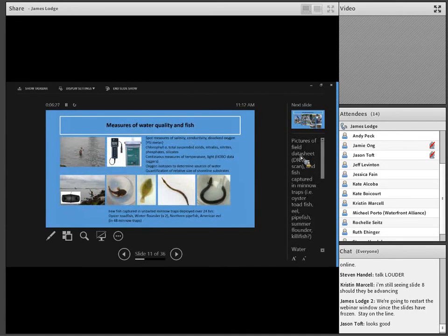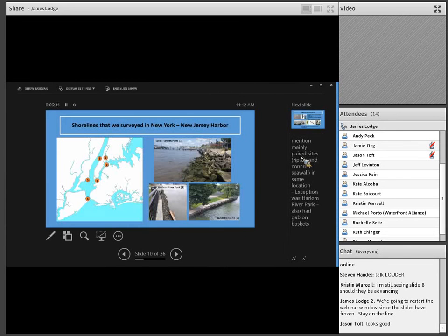And as I said, we had those site clusters, and we had 5 replicate colonisation devices on each of the different shoreline types within each site cluster. So for Harlem River Park, we had 15 colonisation devices, 5 each on shoreline gabion baskets, seawall gabion baskets and riprap, and for all the other ones we had 5 each on seawall and riprap. You can see that these shorelines were quite variable anyway, so this was a nice test of whether our colonisation device worked across different shorelines. Here are the gabion baskets at Harlem River Park, West Harlem Piers riprap, and Randall's Island seawall as examples.